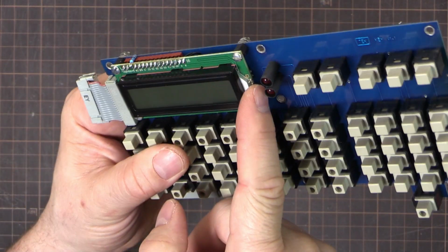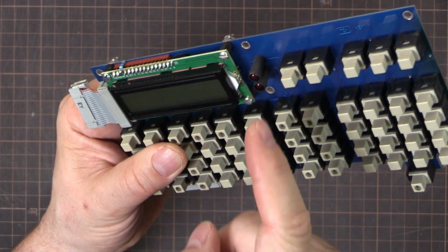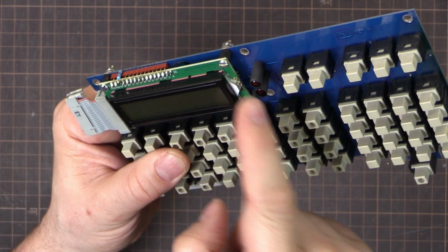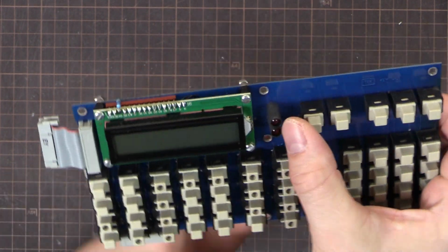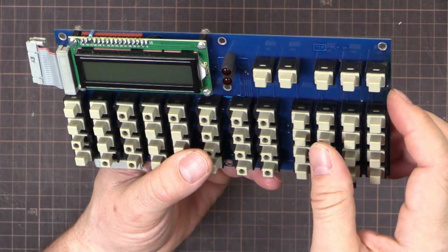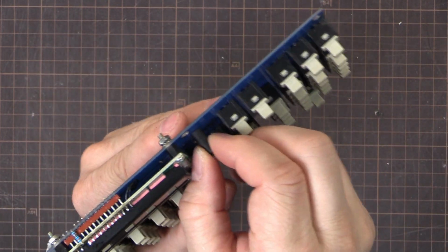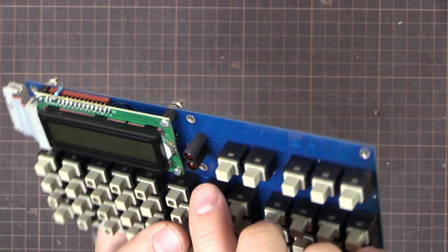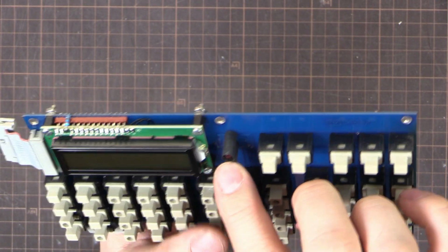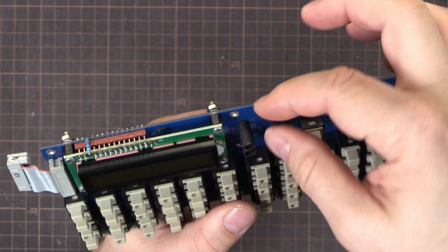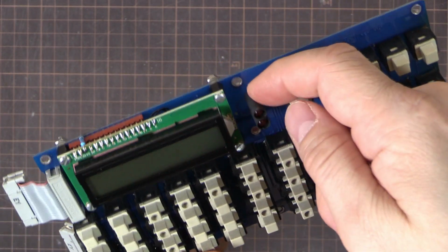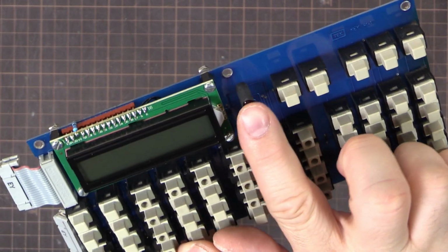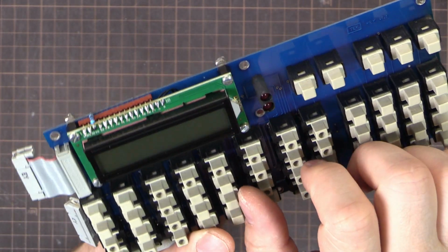Also, the light seems to leak a little bit out of the end of the backlight there, and it shines onto the LEDs, and when the front panel's on, it makes those LEDs kind of look like they're turned on because the light's coming through the LED. So I put some heat shrink there. It's like 5 or 6, maybe 6mm heat shrink, something that will slip over there, and it's about 14mm long. So when that comes up to the front panel, the heat shrink is acting as a light barrier, so that you don't get light leakage coming through.